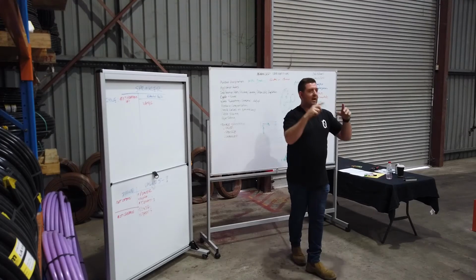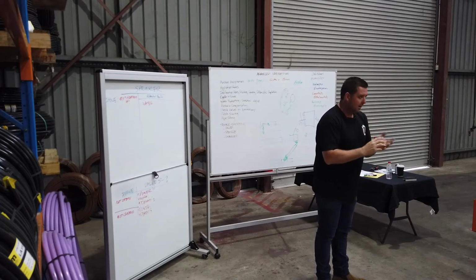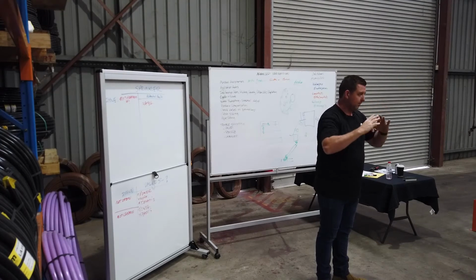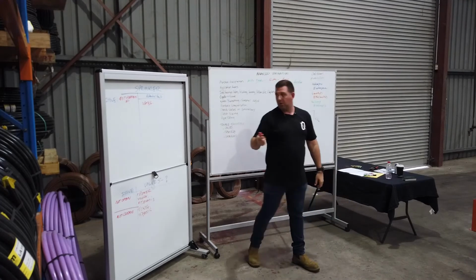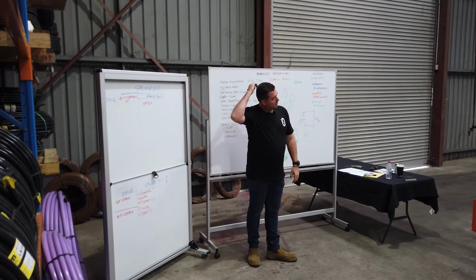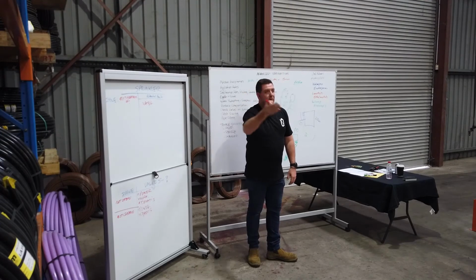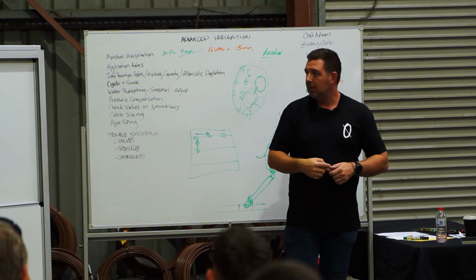So water flushes out between the O-ring of the sprinkler and the sides of the shaft to clean any debris out. And when the sprinkler gets to its full pop-up height, that taper is at its widest and it seals off on the seal, and then you've got the right flow. So when we're designing those systems, we try to design them to about 80% of the required flow. So if we designed that at 16 litres a minute or 15 litres a minute with his 20, he would have been fine.